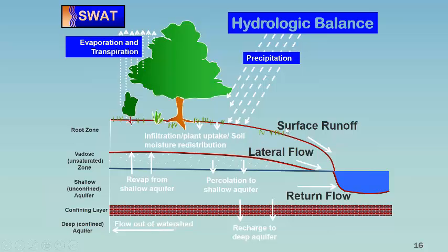For runoff, we have two sets of processes. Either you can use the NRCS curve number approach or the Green and Ampt approach, either in a spatially explicit manner or in a little bit more lumped manner. Then once the water reaches the infiltration, it's going to get distributed across your root zone, and any excess soil moisture will return as a lateral flow.